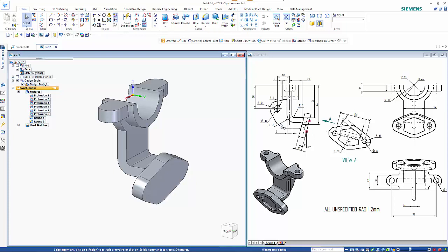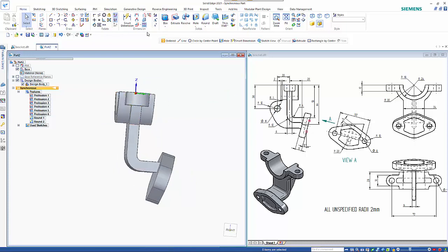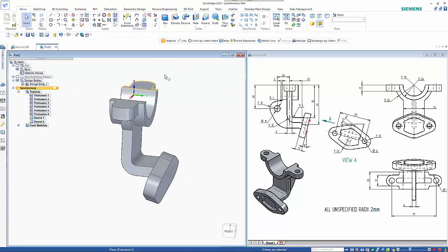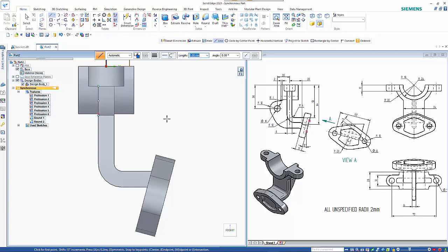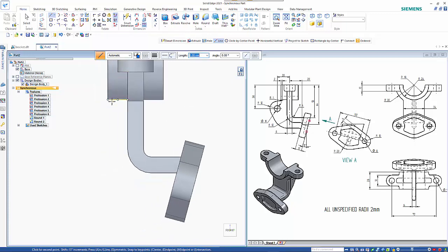So I just need to create this profile on here. So 38 down and 20 out for that, 12 mil radius center, and then it sort of comes into that point there. So it's going to sort of come down off here. So I want to just draw on the ZY plane. So start here, lock the plane. So as you can see, it sort of starts here, drops down across, A key for an arc.